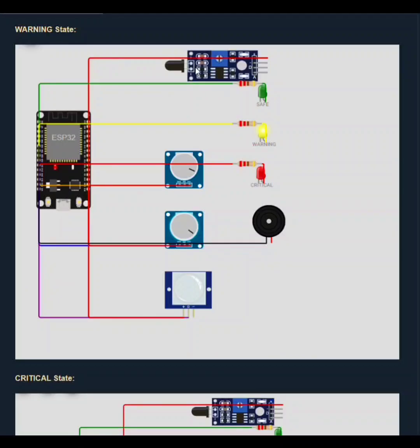Test case 1, fire detection, fire debounce logic. The flame sensor requires five consecutive high readings before confirming a fire event. A single flicker or transient noise never triggers a false alarm. This prevents panic response to sensor noise. And this is test case 2, gas sensor warm up. Warm up suppression for the first 30 seconds after boot: all gas readings are suppressed. MQ series gas sensors have an unknown warm up period. This prevents false critical alerts on startup.